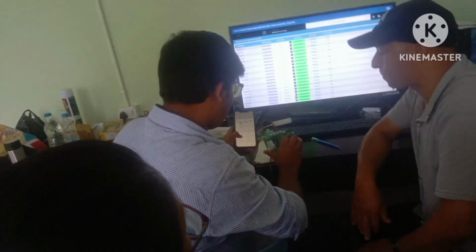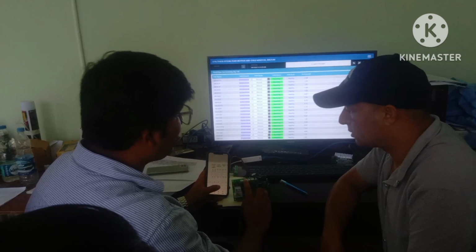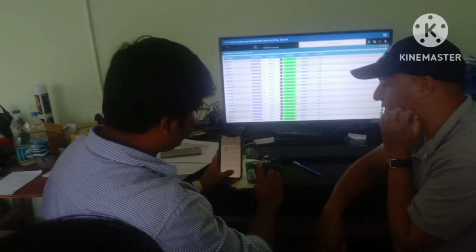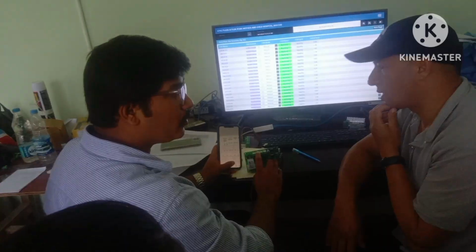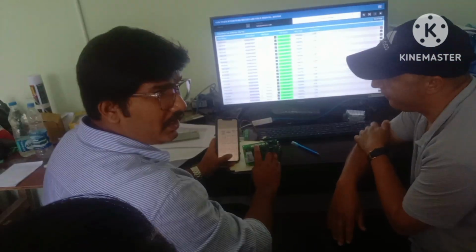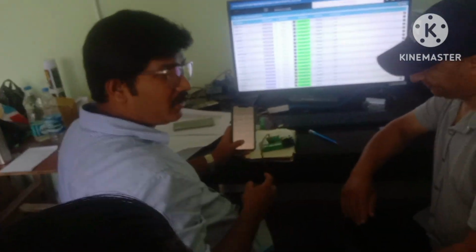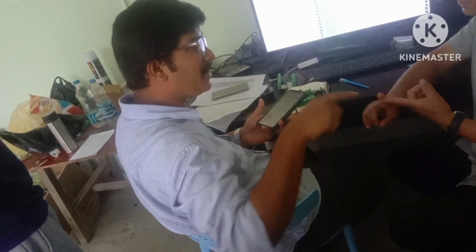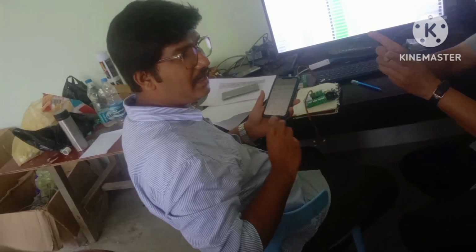First, 10 and 11 stand for auto and manual. Like now it's in manual mode, so I am getting a manual input. In auto there will be another condition: for manual it will be NC, and for auto it will be NO. NO and NC, I hope you know: normally open, normally closed. Whenever you short things, that means we get the command on, the circuit is complete. When you open things, the circuit is not complete, that means it is off.